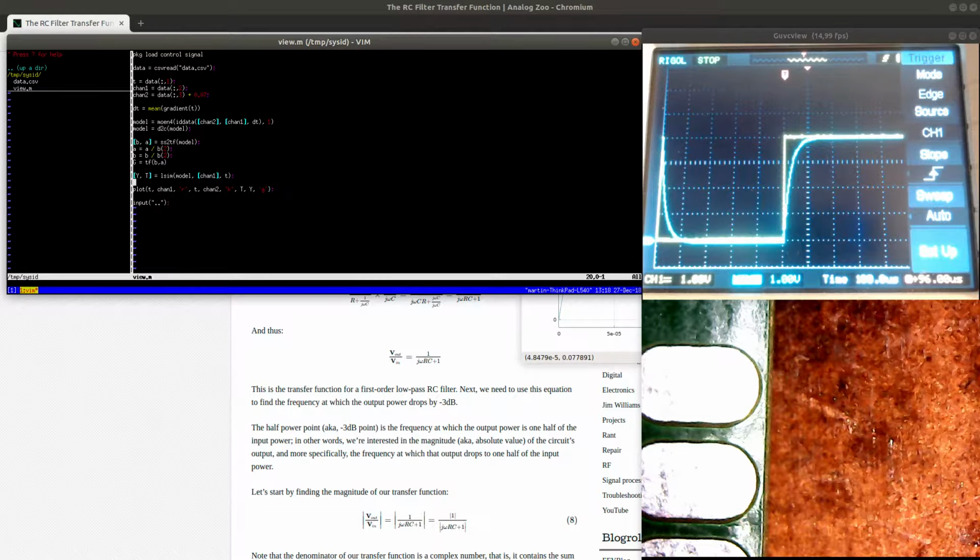To do that, the easiest way is to first decide what time step you're going to run the model at. Typically 1 millisecond is very common. You could run your loop at 1 millisecond, and then just use a discrete model with a 1 millisecond time step.